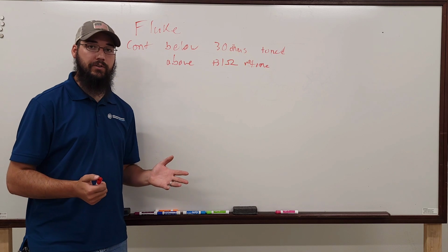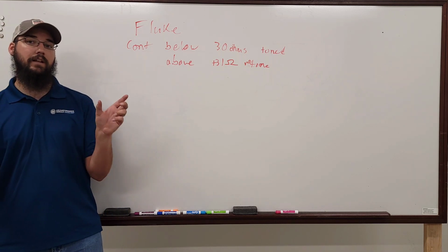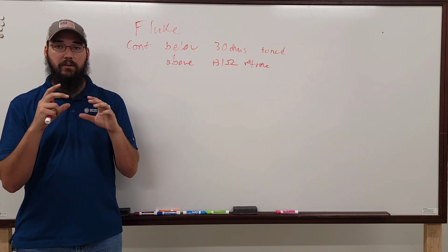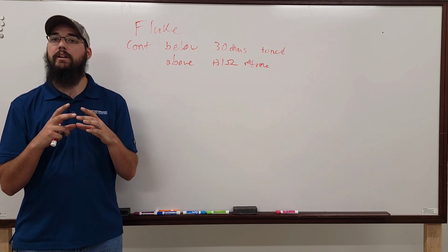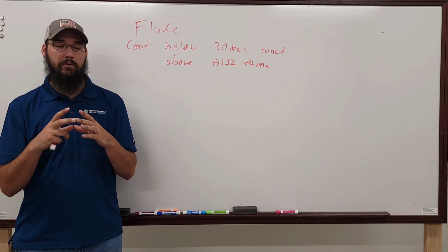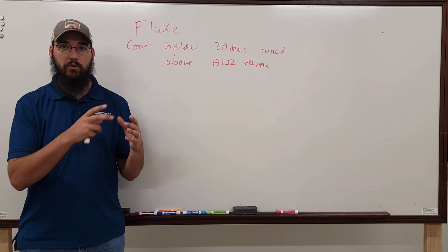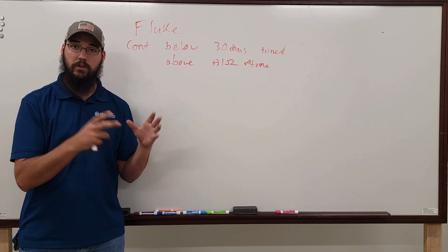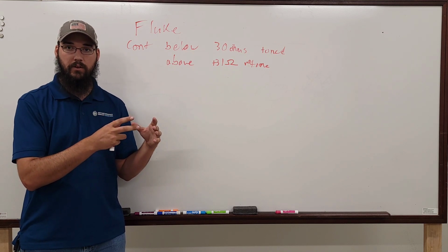In many meters, the continuity and the diode test overlap. That reading you get may be like a volt to DC reading. It won't actually even be your true ohms reading. So in continuity mode, you won't even see what your actual ohms are. Some meters do, some don't.